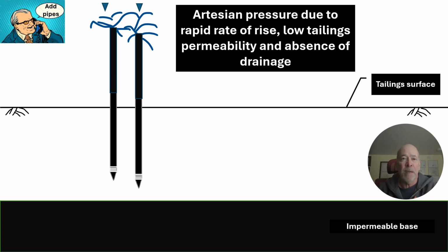And so I really dislike having a single piezometer trying to tell me something. And you can probably see why with these two different site investigations. And remember back to the spring and dashpot, this would be where the load is applied and the water is trying to get out as fast as it can, but our clay layer's keeping it in there, right? So we're a long way from consolidating this thing under normal conditions. So anyway, that was the tale of two site investigations.